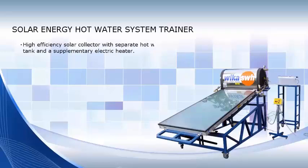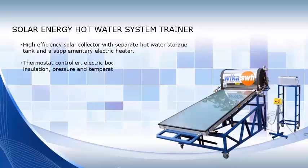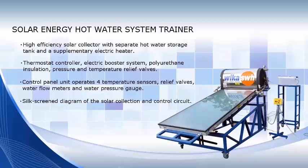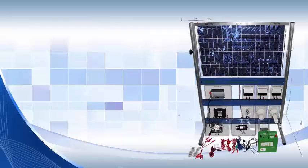This photo shows Labtech's solar energy hot water system trainer. This trainer is designed to represent a state-of-the-art solar hot water heating system now popular for use in residential and commercial applications. This trainer features a high-efficiency solar collector with an integral hot water storage tank and a supplementary electric heater. The unit also comes complete with a thermostat controller, electric booster system, polyurethane insulation, pressure and temperature relief valves. The system also includes a control panel unit that features 4 temperature sensors, water flow meter, and water pressure gauge.